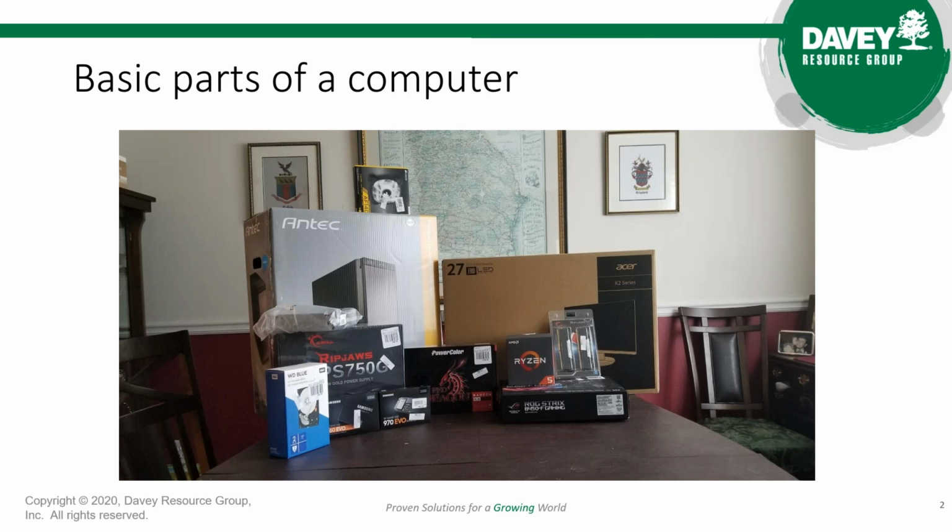Because I can tell you right now, and I'm going to use Esri software as the primary example because that's what I'm most familiar with, just because your computer is capable of running ArcMap and ArcCatalog now without a whole lot of issue, that doesn't mean that it will run things like ArcGIS Pro successfully, because these new applications have a much broader hardware requirement in order to support all the new capabilities that they bring to the table.